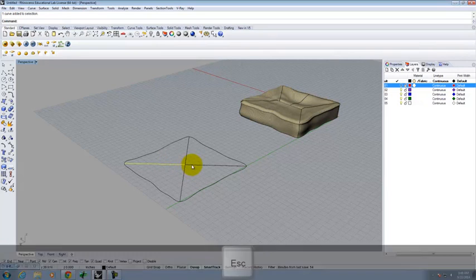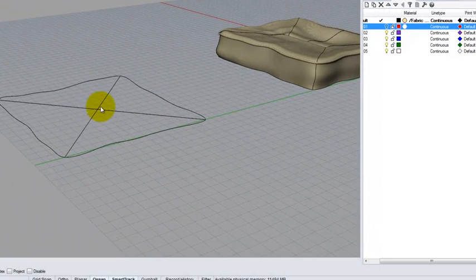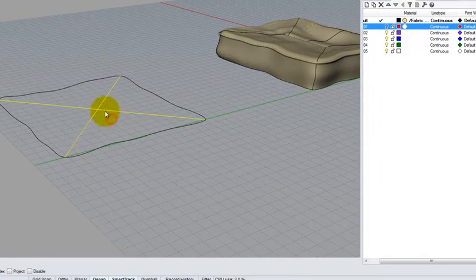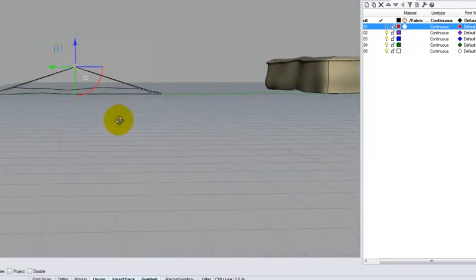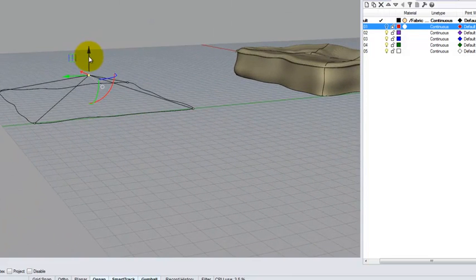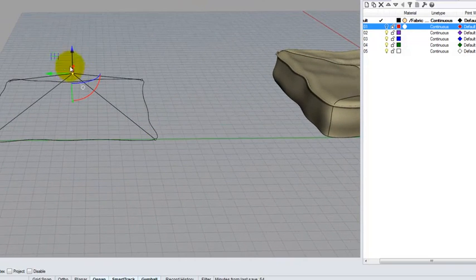That was important. Okay. Now what I'm going to do, and I'm only going to do the top half of this for right now, I'm going to look at these objects. I'm going to turn my points on, and so we see that we have a point that's at the center. I've selected those, and I'm going to move these points up to create one half of the pillow. Okay, and I know they're not quite ideal yet. They're straight line segments.